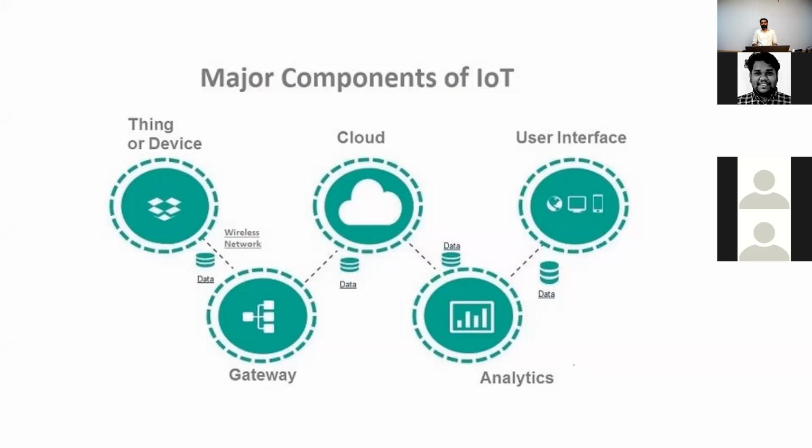It may be either non-invasive or invasive type sensors, or analog or digital type sensors. Depending upon these microcontroller devices or your hardware deployment platforms, we have to choose what type of sensors are most suitable for your applications. For example, when we are dealing with digital devices, microcontrollers, microprocessors or GPU units, we know that definitely it will accept only digital information from the outside.